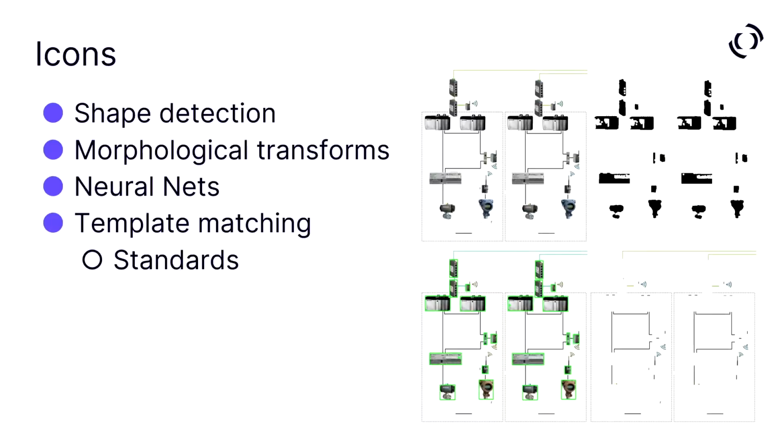And finally, template matching. You can actually do this, not so much on the network diagrams where people seem to just Google image search a computer and throw it in there. With the P&IDs and the loop drawings, these things actually tend to follow standards pretty well. And so once you find a specific subset of pixels that represents a valve or a pump or something like that, you can put that in and just match it almost verbatim, and you'll get some good results from that.